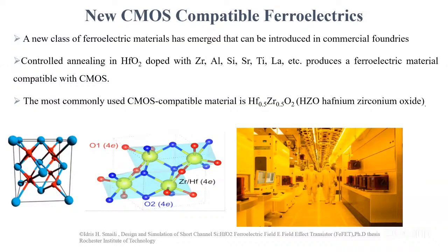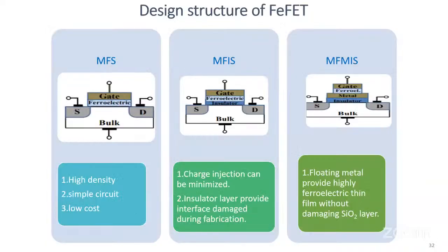So FEFETs are now developed which are CMOS compatible, and they can be developed with different kinds of stacks. One of them is called the metal ferroelectric semiconductor stack, where we have a ferroelectric layer between the gate and the bulk. Then we have the metal ferroelectric insulator semiconductor, which is the MFIS stack, where we have an insulator as well as ferroelectric material.